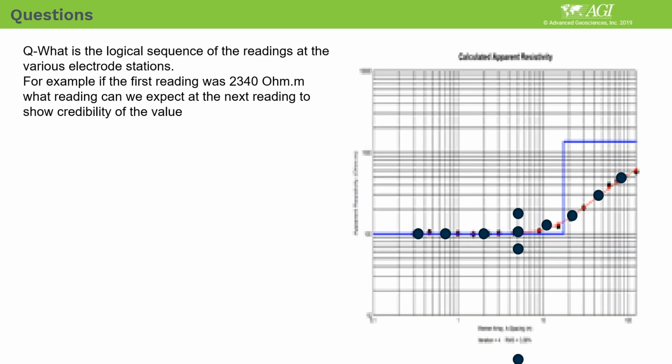That means if you have 500 meters of salty water, and you put your cable under the water, you measure it. So if you're in that environment, or very close to the seaside, with very salty, hypersaline water in the area, then you consider your depth of investigation as 15% of the maximum electric span, which is typically your maximum spread. So if I'm expanding my cable 100 meters, I can investigate about 15% of that.